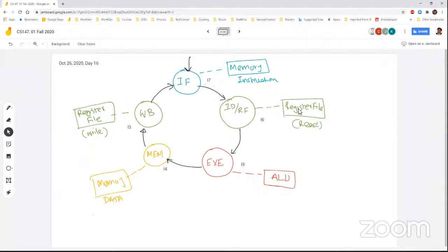Okay, now next is that, as we saw, if the instructions can be fetched one after another and pushed through this circle of life, I would say, for this instruction execution, then it will gain like 5x speedup, right? But why can we not actually gain 5x? There comes a different type of hazard: structural hazard, data hazard, control hazard.